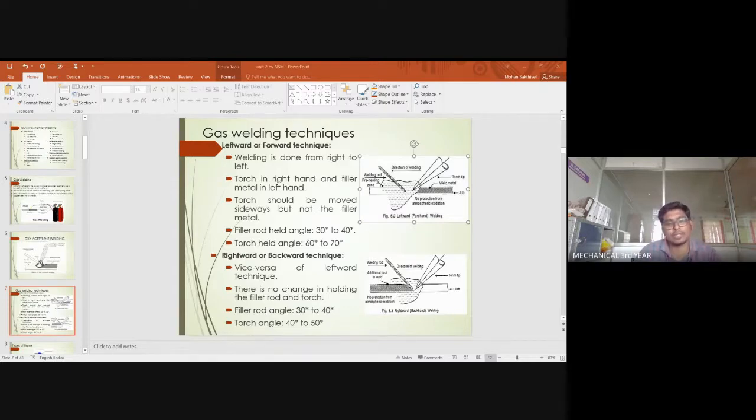So you can see over here in this image also, since the tungsten electrode is getting heated up continuously, there may be water jackets available in this particular area. So in order to cool down the temperature of your tungsten electrode, you will be using cooling jackets to bring the temperature down. The same thing is also available in the case of MIG welding. So most of the things are similar when compared to your TIG welding.